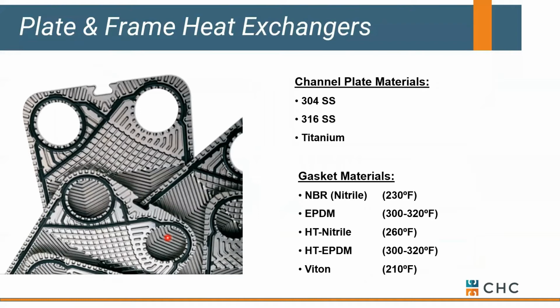Now, typically, plates are 304 or 316. Sometimes you're into a pool application, maybe a saltwater pool or high chlorides, where you want to look at titanium. That's certainly an option. I want to say we're not building a space shuttle here, but it's typically the same cost as a double wall plate and frame. So, kind of two plates.